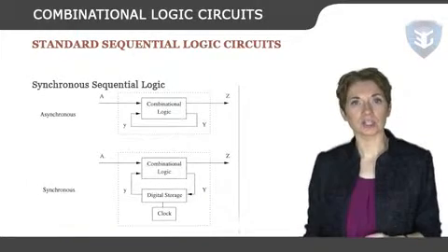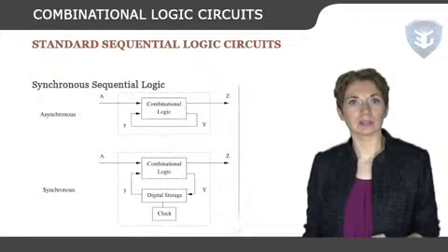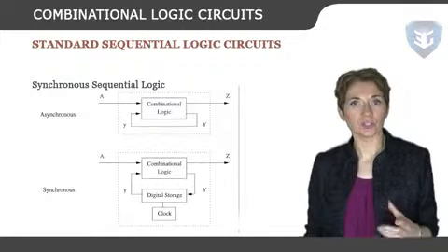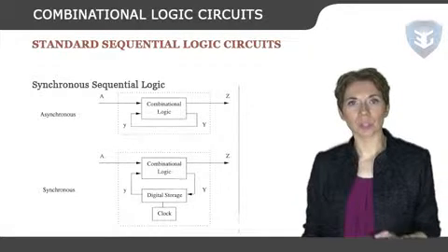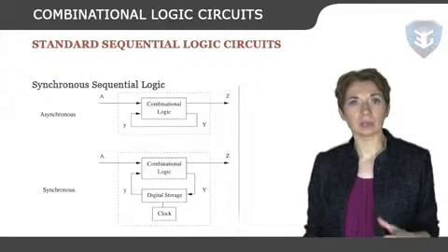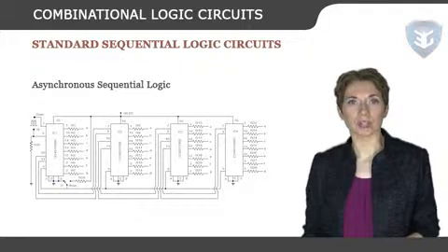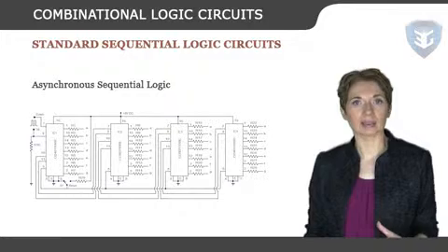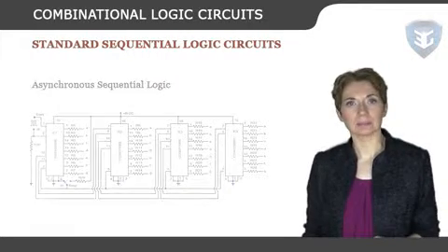Synchronous sequential logic. Nearly all sequential logic today is clocked or synchronous logic. There is a clock signal, and all internal memory, the internal state, changes only on a clock edge. The basic storage element in sequential logic is the flip-flop. The main advantage of synchronous logic is its simplicity. Asynchronous sequential logic. Asynchronous sequential logic expresses memorizing effect by fixing moments of time when digital device changes its state.